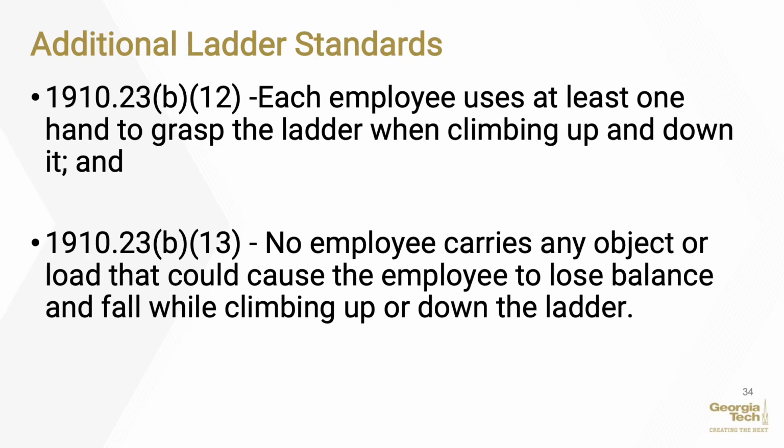Here are some additional OSHA standards that are important to follow. Each employee uses at least one hand to grasp the ladder when climbing up and down, and no employee carries any object or load that could cause the employee to lose balance and fall while climbing up or down the ladder.